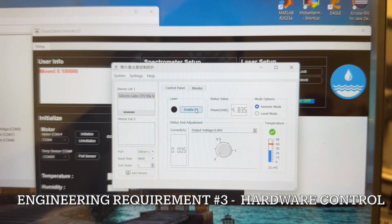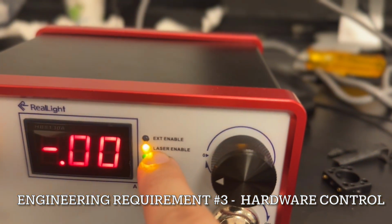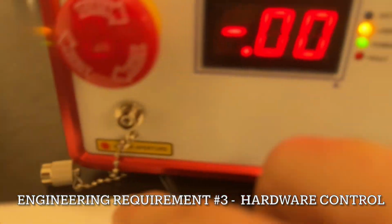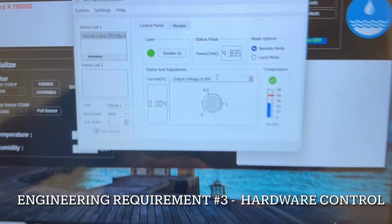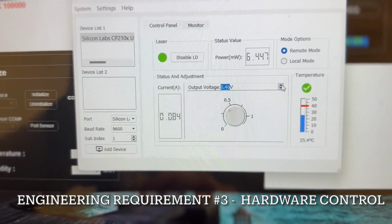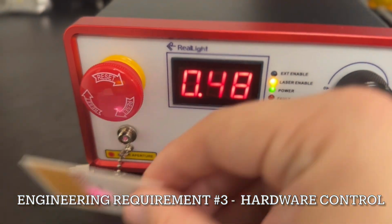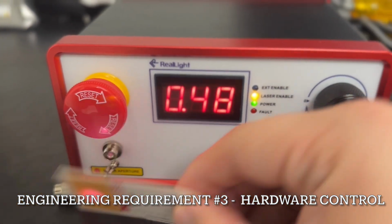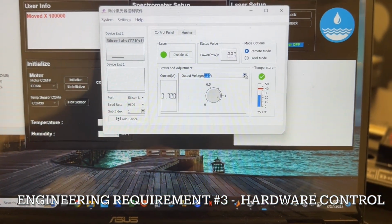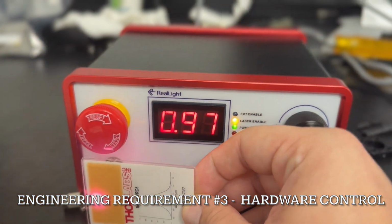First thing I'm going to do is enable the laser. So as you can see here, there's a light turned on, laser enabled. However, there's no output because I haven't given it any output voltage. So I'm going to increase this to halfway, which is 0.6 volts. And you can clearly see that the amps went up and there's a laser coming out of this. And when I crank this up to the max, it'll be much brighter, as you can tell.